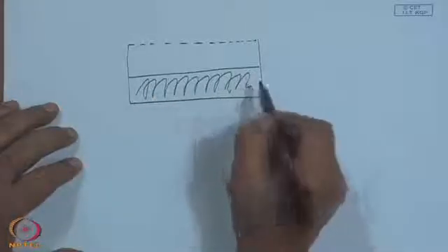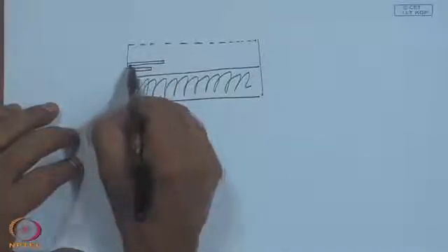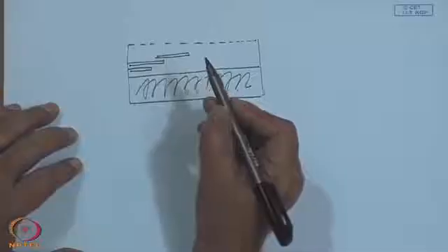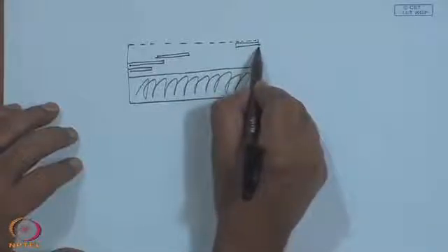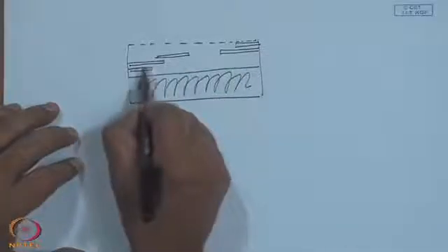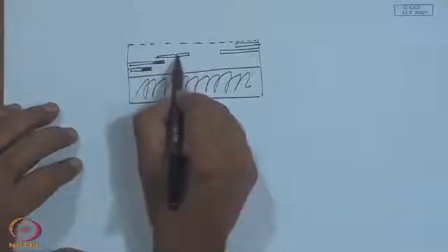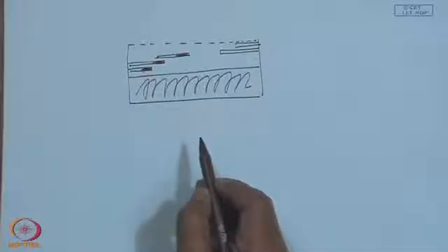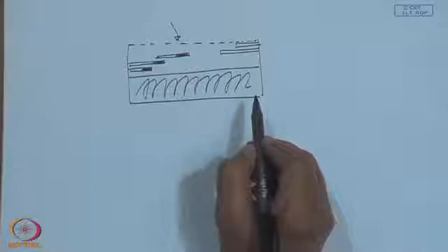The bottom is insulated, and you have got plates, then another here, like this, up to here again, then this may protrude a little more with a black painted portion and a transparent portion, one overlapping the other, so that the transparent portions will be transmitting the solar radiation falling on the top surface, whereas the black one will be absorbing the solar radiation.